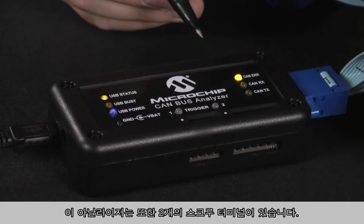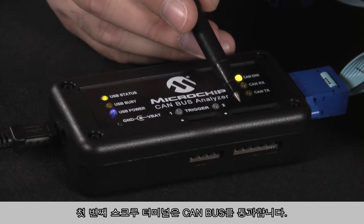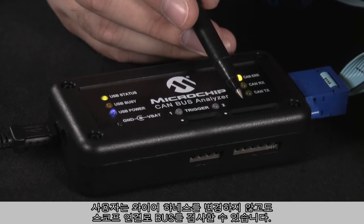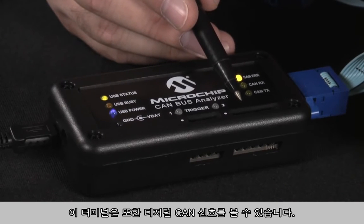The analyzer also has two screw terminals. This first screw terminal provides a pass-through through the CAN bus. This allows the user to probe the bus without modifying the wire harness just for a scope connection. This terminal also allows the user to view digital CAN signals.